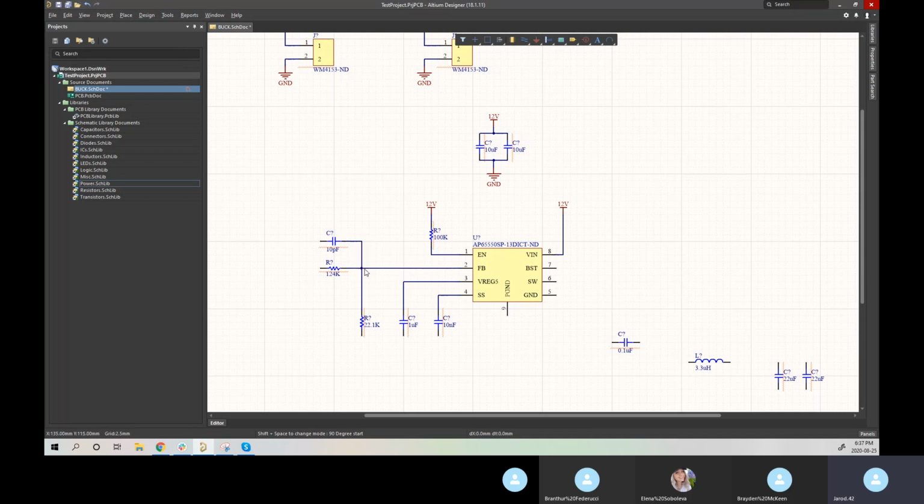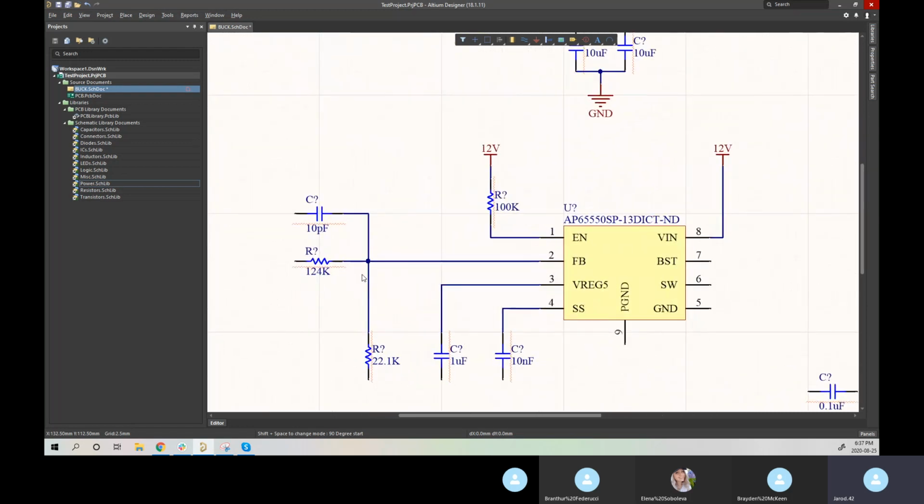So here at this point, we want to avoid any 4-point nodes, or cross intersections, just because it can be confusing sometimes, especially in designs that have more stuff going on, more crossovers and components and everything.